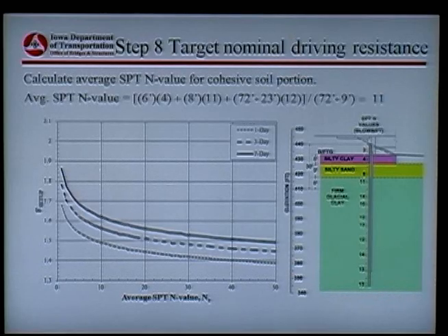As blow counts get lower, which means the clay is getting softer, the setup is higher. Also notice that the spread between the lines from 1 day to 3 days, only a 2 day incremental increase, is larger than the spread between 3 days and 7 days. So this is twice the amount of time change, and it's even smaller. The lesson learned there is most of our setup occurs in the first day or two.